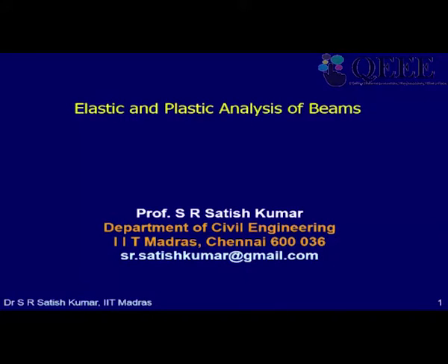Today I'll be covering elastic and plastic analysis of beams, and after that something called laterally restrained beams. Then I'll be proceeding tomorrow to laterally unrestrained beams and design of plate girders. In laterally unrestrained beams, a small part will be covered on gantry girders. As such, gantry girders are basically laterally unrestrained beams, and they do have, of course, some problems because of the impact factors and the fatigue induced by the cranes.